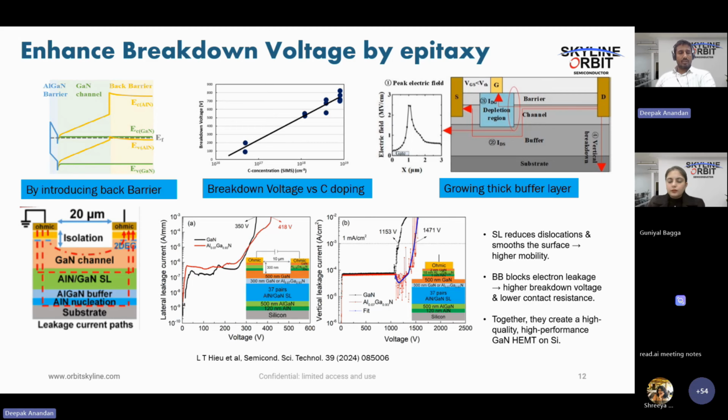The high quality gallium nitride is basically naturally n-type. So when the buffer has n-type carriers, it has to be compensated and it should become a highly resistive layer. So how to make that? You have to do the doping of carbon or iron so that it will attract the free carriers in the buffer layer. Then the buffer layer will become more resistive.